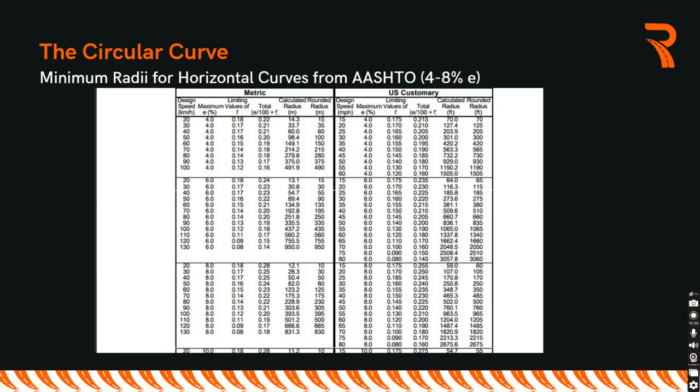So you can see when you're increasing the super elevation, the banking of the road, it means you have the allowance to reduce the radius. This is a skill that is mostly used to limit the design parameters, especially where you don't have sufficient parcels of land to work with, or there's a limitation in space. If the curve is pretty tight, then you can increase super elevation at that specific point. That's one.